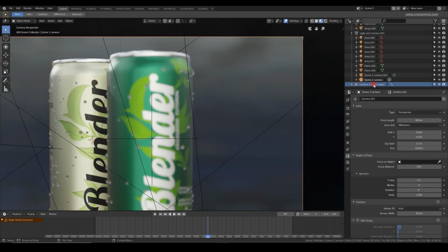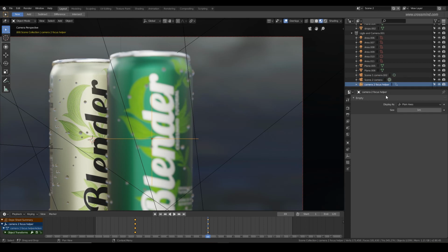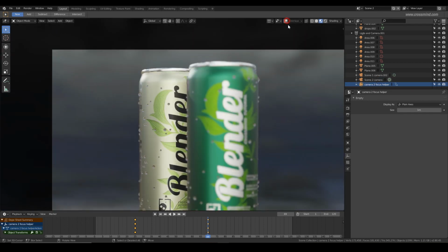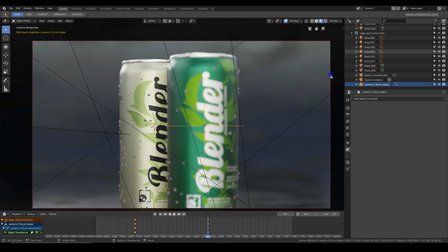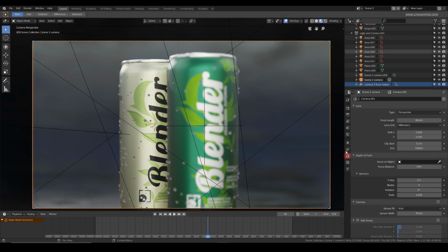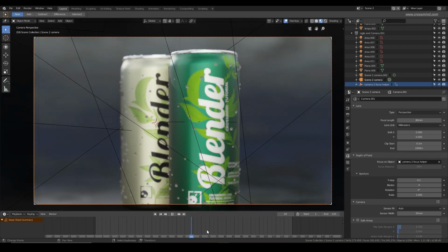I'll select the camera and give it slight motion. Unlike the first shot, there will be slight motion in the camera here. Camera will move down a bit. First let's just assign our focus object. In case you're having difficulties, just type in the name of the object we created. So yeah, as you can see, the shift of the focus is happening here.